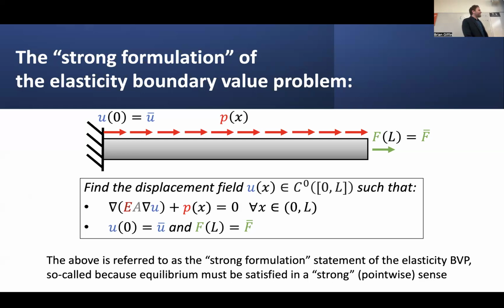which states that we have to satisfy this governing differential equation as posed and seen here in this pointwise sense. And this particular format for solving the strong formulation of a boundary value problem involves all of these extra problems that I've said. It imposes some artificial requirements on the smoothness of the internal force field, and it limits the types of solutions that we can actually admit as solutions to this particular boundary value problem. So we have to find a workaround to that.